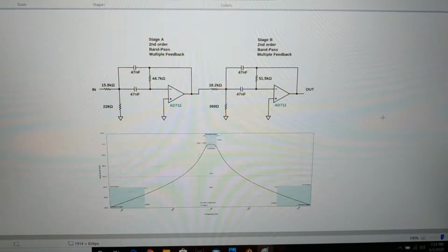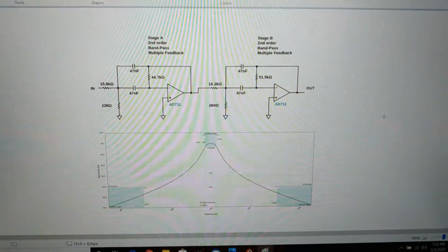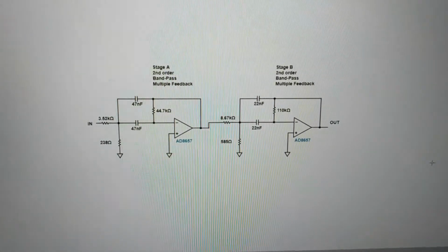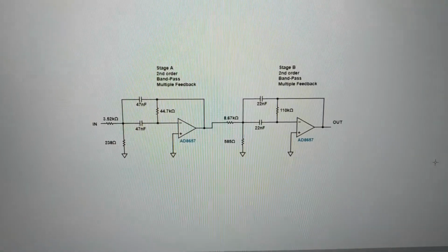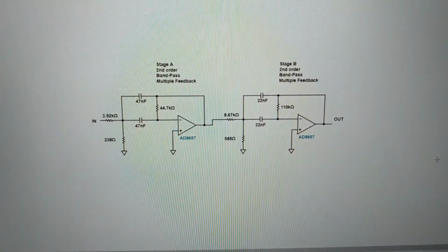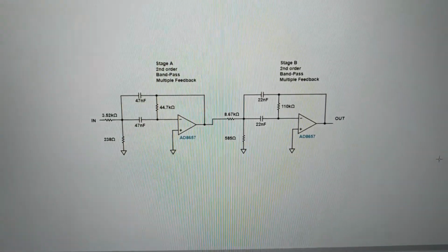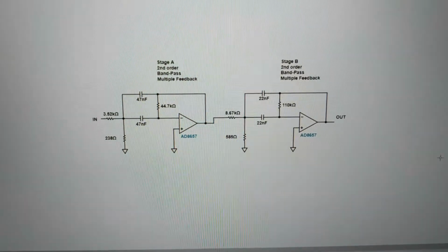However, we realized that we could obtain a higher range of features by changing the resistor and capacitor values. One of the features we figured we could add to our bandpass filter was to have the filter be capable of not only filtering out frequencies, but also amplifying signals. So our solution was to use the 20 times gain filter, as shown in the schematic here. This filter worked reasonably well for filtering purposes.